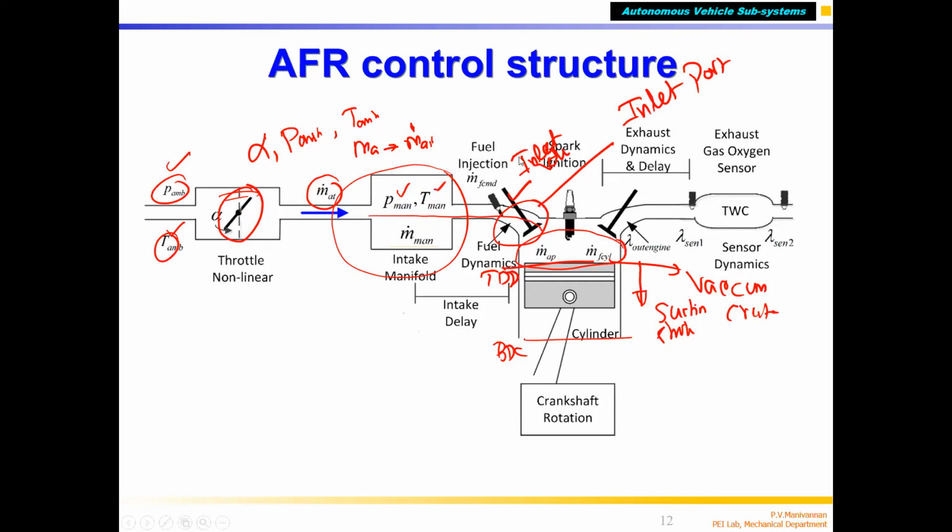Correct. So this is called the pressure at the manifold, and the temperature at the manifold, inside the manifold. This is the pressure of the air inside the manifold. This is the atmosphere outside. Inside this one, because of the restriction, there's a pipe, there are restrictions. Pressure changes, and the temperature changes. When restricted, air may be compressed, velocity increases. Due to that, there will be a pressure drop and a temperature drop.